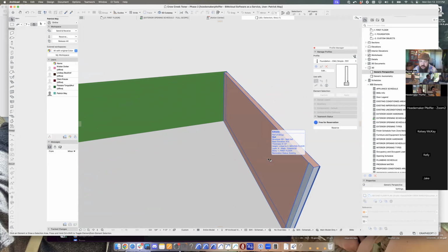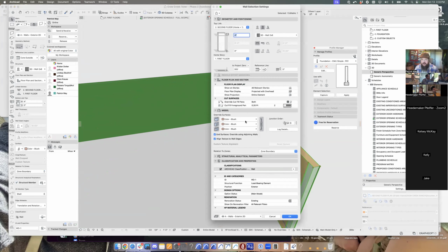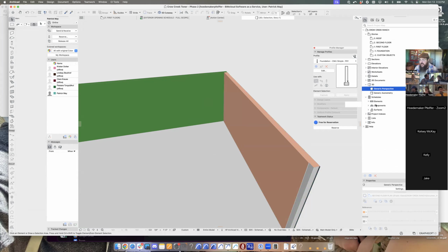It's really tricky to, it's not impossible, but it's tricky to get accurate surfaces. And beyond that, the naming of those surfaces, you're pulling that exact attribute name into your schedule if you're using the automated attribute schedule, right? So going back to where we started off, you can technically schedule surfaces. It's just really difficult to filter that down to just what you want and just for the rooms that you want. It's usually so much maintenance and struggle that by the time you get it figured out, it changes and you've got to go figure it out again. It's so time consuming that you could do it in Excel faster than you could do it with those automated schedules.